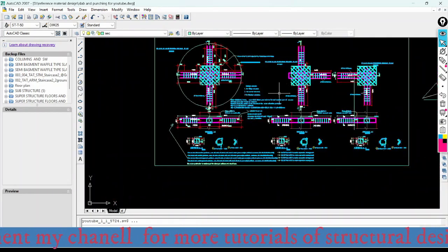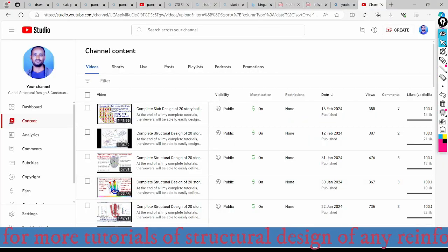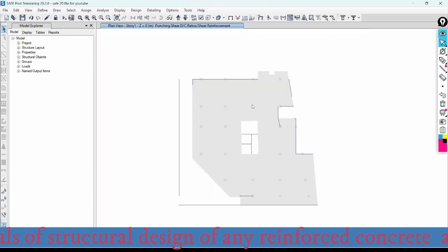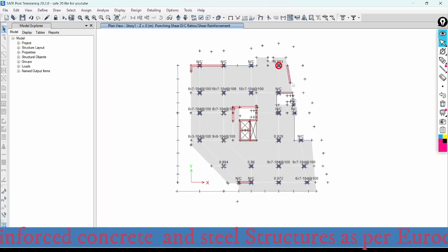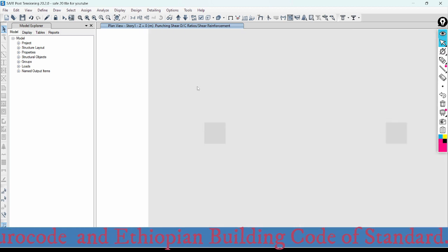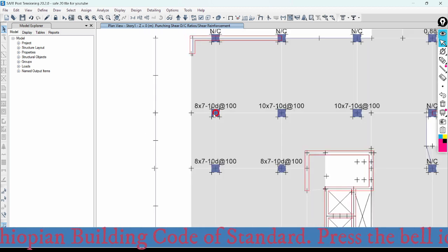So basically our slab here, our floor, will have three types of columns. The first one is the corner column, the edge column, and the interior column. And we may have a column which will be located closer to the edges of the slab. In this case, we need to place our reinforcement bar ties in two directions. That is here in this direction and in this direction.